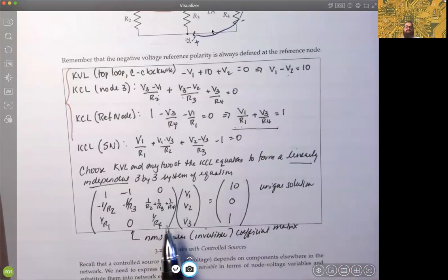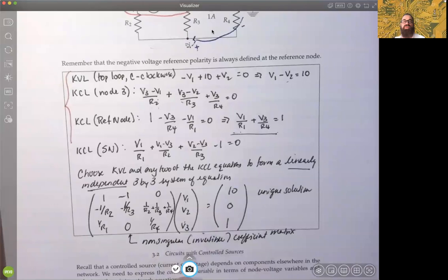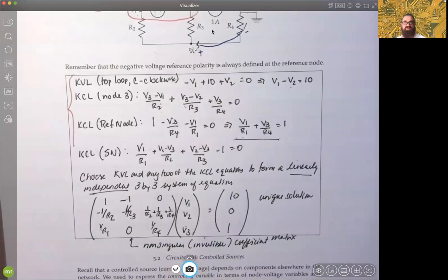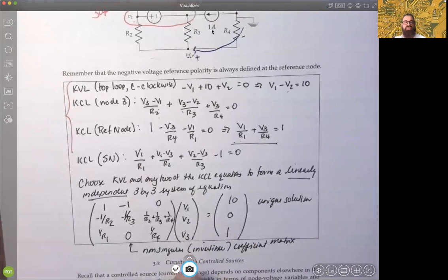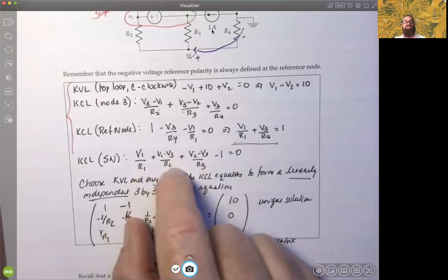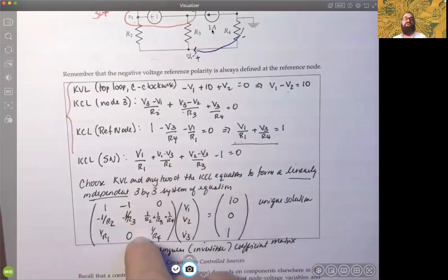And again, you would have the resistances, you set the equations up and then use your matrix solver, MATLAB, calculator, Python, whatever, and there's your right-hand side vector and it would produce the nodal voltages that we need. So lots of ways of creating current equations and voltage equations here. So I'm just trying to illustrate the fact that the supernode is one option. Sometimes you don't need it, but sometimes it's just as easy, and one could take the supernode and let it be one of the rows and it'll all be fine, okay?